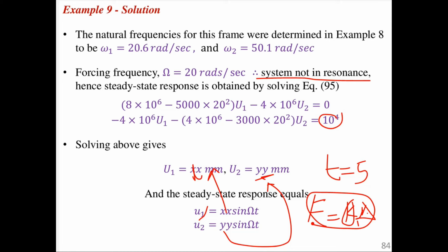And from the force, if you ask about what is the stress, the dynamic stress, now from the force, you can be able to get what is the stress if you are given maybe the section properties of a structure, or you can even use the equation of simple bending.